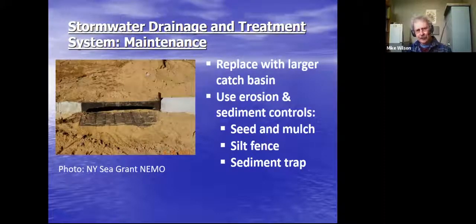If we have areas that we're cleaning on an excessive schedule, an excessive amount of times, you can replace the catch basins with a larger catch basin. You can use erosion and sediment controls.